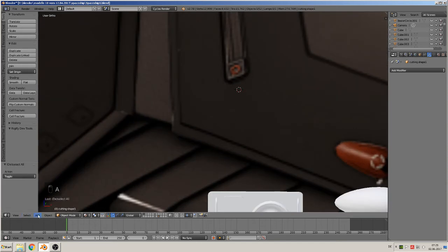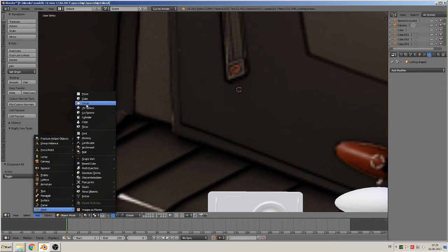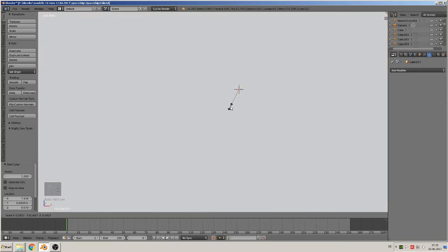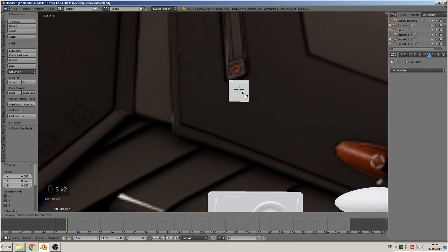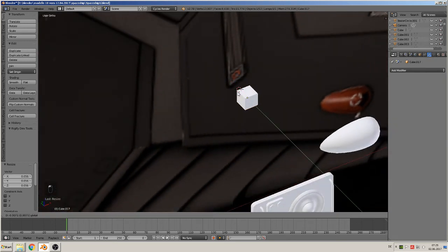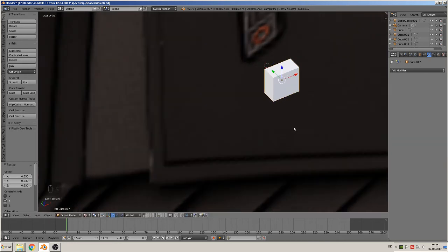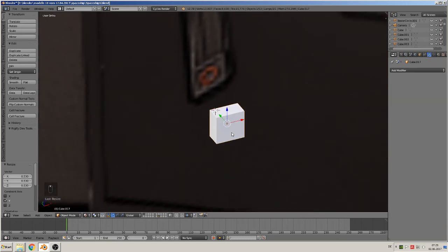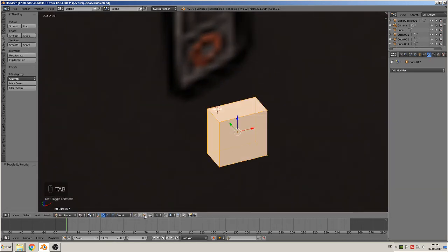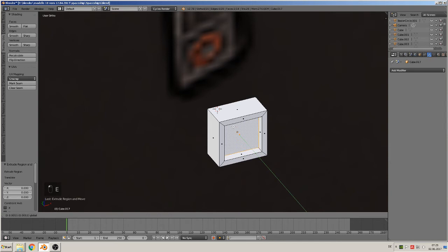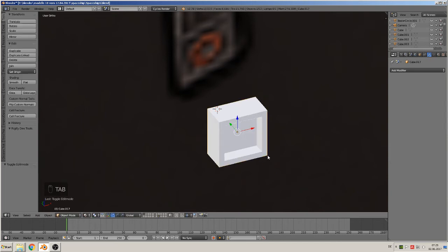So we put in there add mesh cube, scale down to that side maybe, then scale in the Y a little, then we go edit mode by hitting Tab, mark the front face, disable background selection, extrude, scale to get here a little space between, extrude to the Y. We go into the material, that's good.